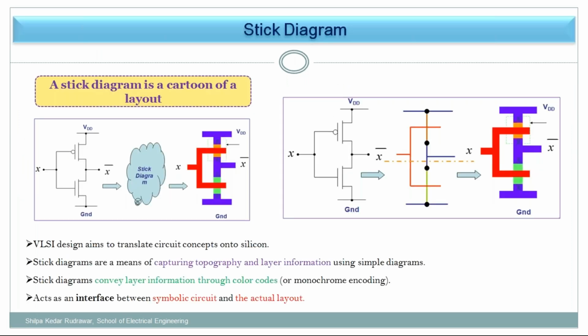Now you are able to see some colorful diagram. This diagram we are implementing on microwind. Okay, the first practical is of the inverter, the CMOS inverter. So you know the PMOS and NMOS connection for the inverter, as we have gone through it in the last PPTs. That network you need to implement, and for that network you need to draw the drain, source, gate notation properly, as I told you earlier.